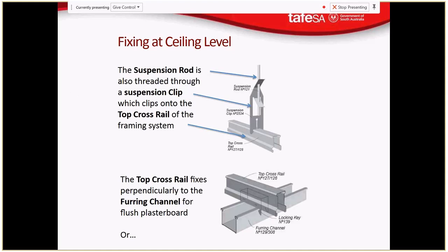When we have a suspended tile system, typically we'll have a deeper top rail, and just for the ease of drawing, I'll keep that small, and then our perpendicular rails. So this is the one we've got our clip attached to, and suspended from the ceiling. Then our perpendicular rails are much shallower, but the bottom of our rails sits flush, so our tile can sit inside that. So they have fixings here.